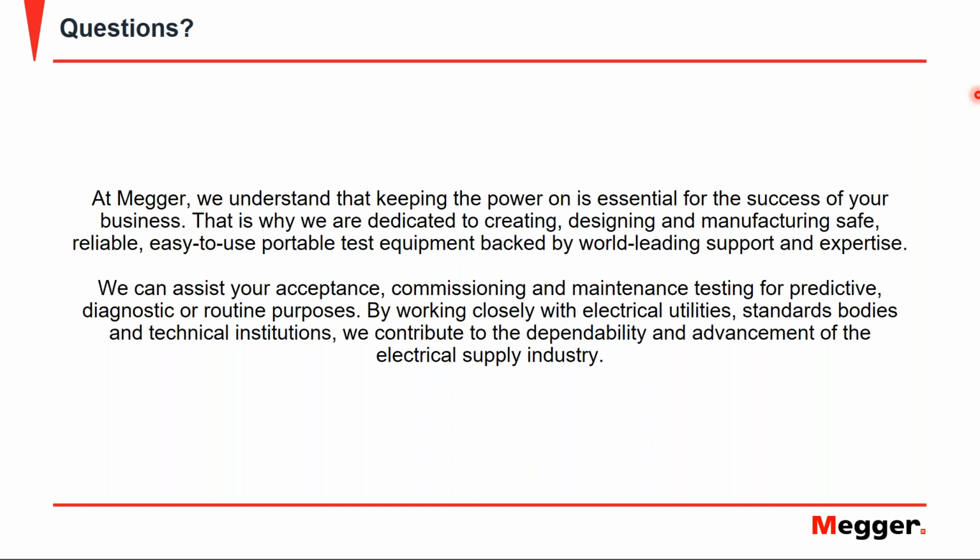So whenever you're doing this type of testing, if you see anything with sharp edges on the connection, or loose strands because the cable termination was installed incorrectly, you're going to want to address those prior to taking your partial discharge measurements. Like I said earlier, all that's going to do is show that you have partial discharge while you're doing your testing, and that's not the point of what we're trying to do. We're trying to actually find points of valid partial discharge. So it's very important that you're meticulous about the way that you set up the cable prior to performing these measurements.